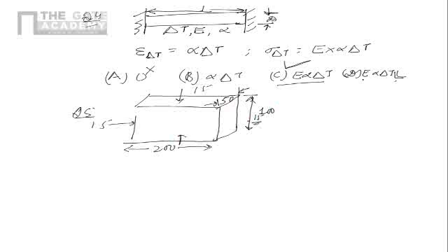Also the Young's modulus is given as 200 GPa and the Poisson's ratio is given as 0.3, right? So these have again been provided to us. To get the answer here, we need to get the bulk modulus of the material. Now the bulk modulus of the material K is given by E upon 3 times 1 minus 2 nu. That's the bulk modulus of the material.